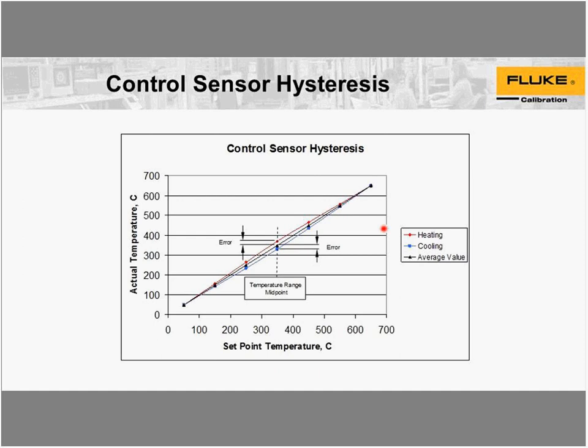So what's going on? The temperature sensor in the dry well calibrator is an industrial sensor. What's an industrial sensor? It's been built so that if that sensor is shocked in some way, it'll have less chance of shifting in temperature.